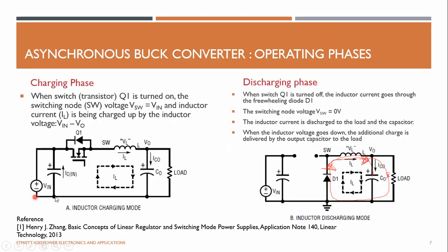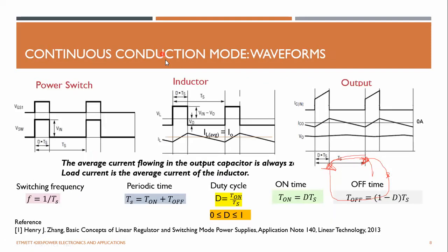So when you increase the frequency, the size of the components goes down. Which means if you're designing a buck converter at, let's say, 100 kilohertz, you need very big inductors, so your power supply will be like this, right? If you switch at 1 megahertz, you can just reduce it to like this. It has only a very small inductor and a very small capacitor.